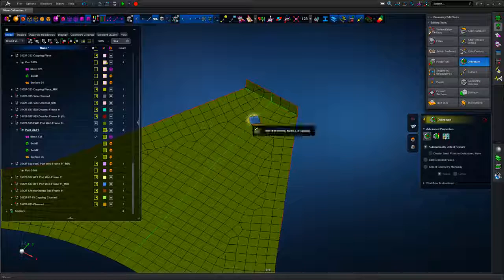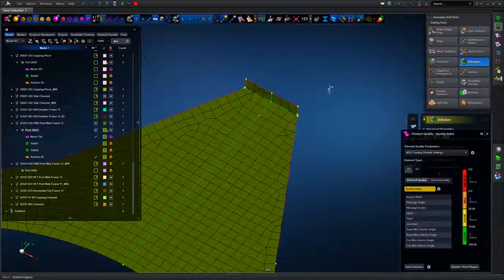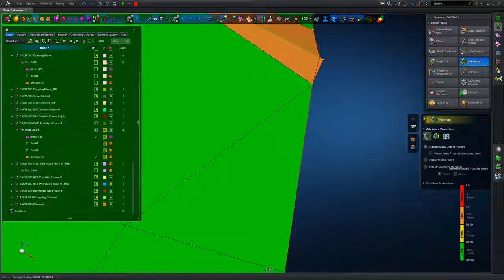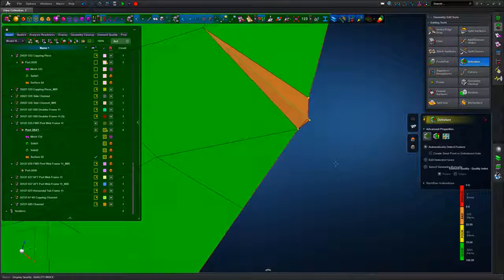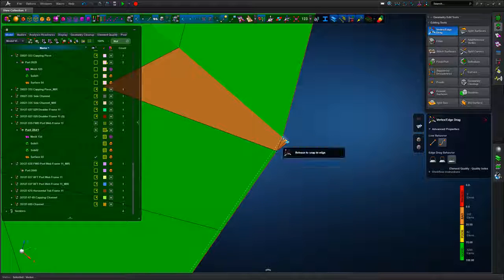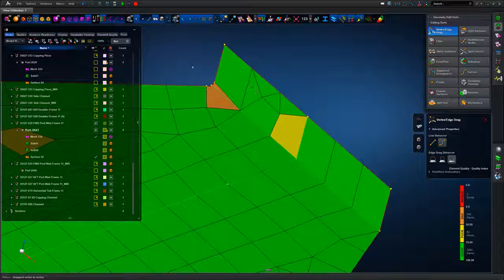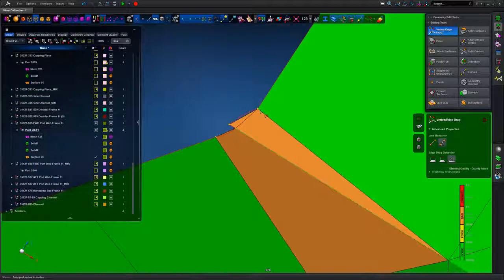Defeature on a manual basis now just to remove the hole. And we can see as we defeature the mesh updates, turning the element quality on, and now we can start to make some sense of this mesh geometry and mesh definition on the single part level. Following the defeaturing operation, we're now going to use the vertex edge drag tool, so we can see the guidelines, and it's simply a case of manipulating the geometry. The mesh automatically updates and the element quality automatically updates, so we've got almost real-time feedback in terms of any model manipulation we make at this level.